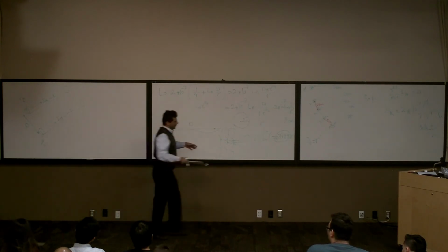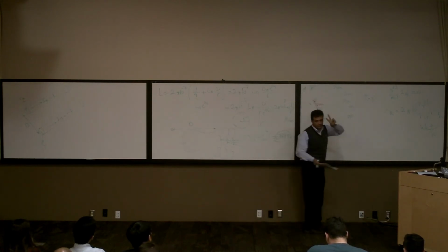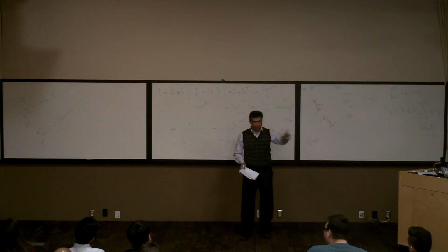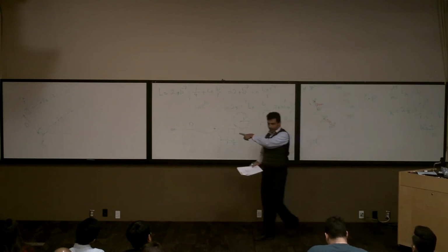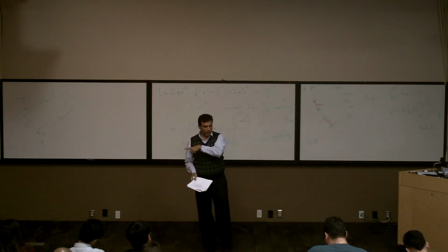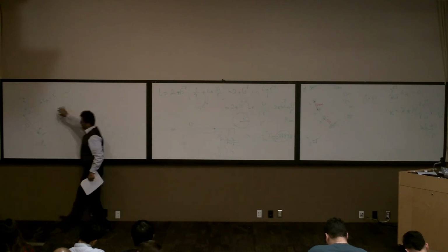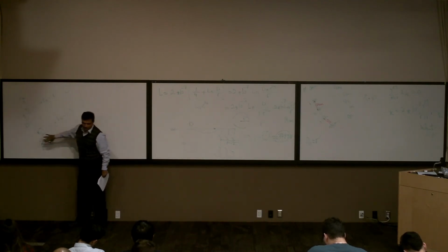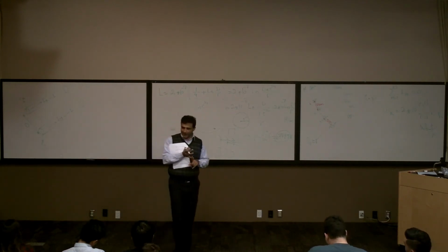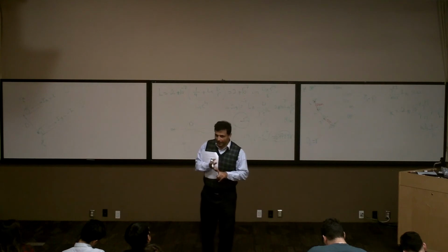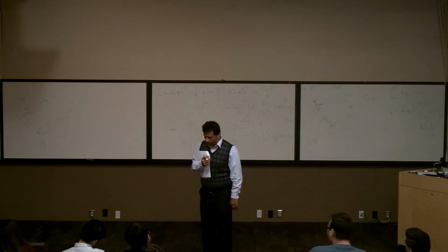Now I'm going to go back here. Basically, instead of having N conductors, I have just two conductors now, right? So I can calculate lambda x for conductor x, and lambda y for conductor y. I can calculate the inductance for this wire, the inductance for that wire, and add them together. I can calculate Lx, I can calculate Ly, and add them together. The total inductance is Lx plus Ly, right?